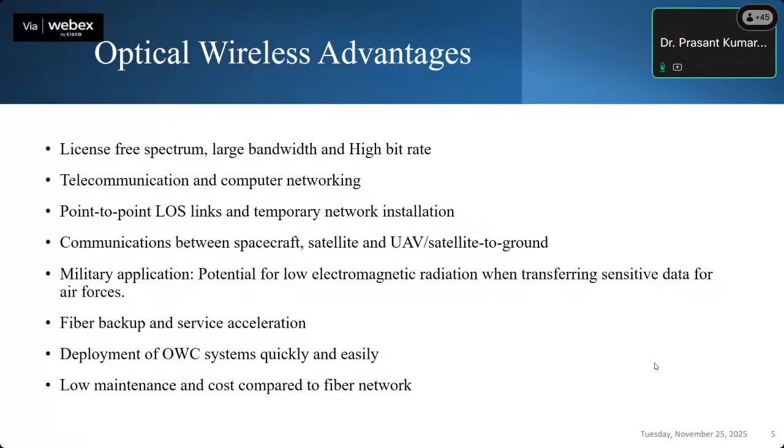So we need to adopt some robust techniques. Some research groups are working on different encryption for optical wireless, but that makes the system complex. So we are working here on a scheme called a chaos aided secure optical communication system, whereby instead of generating the encryption and then decrypting it at the receiver side, we are trying to add chaos signals to the transmitted information before we transmit over the channel. So once this chaos is added, the chaos will now mask the signal to be transmitted.